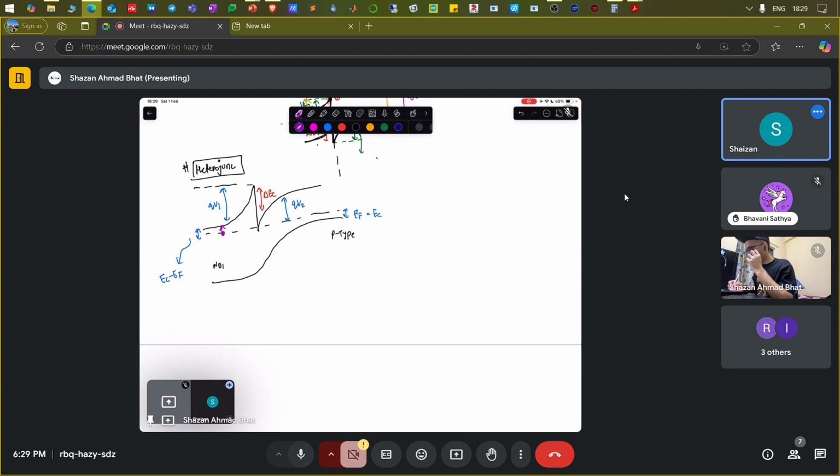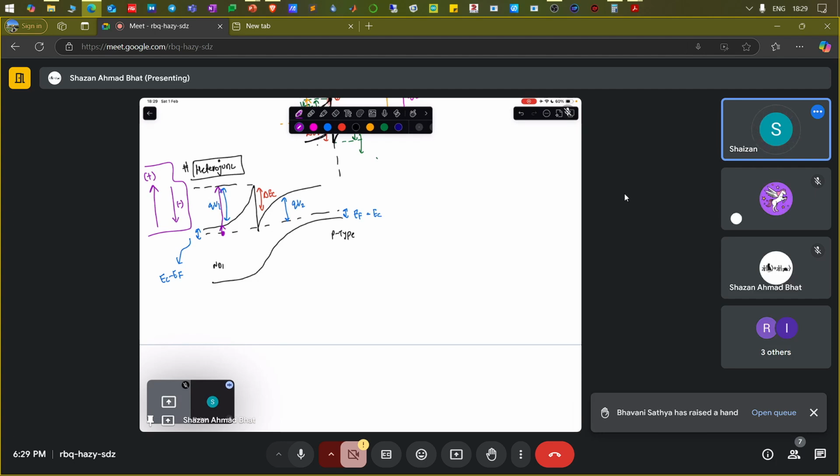Then you go up again, and consider the convention. Whenever you go up, you consider that as positive convention, and you sum up those voltages. If you go down, you consider that as negative. This is the convention we are going to follow. You can do the opposite, but you have to maintain the convention. You can consider up as negative, down as positive. You will arrive at the same answer. At the end, you have to sum up all of the voltage in a loop.